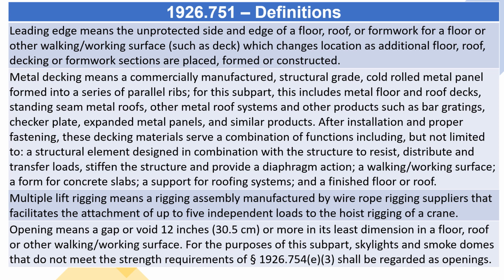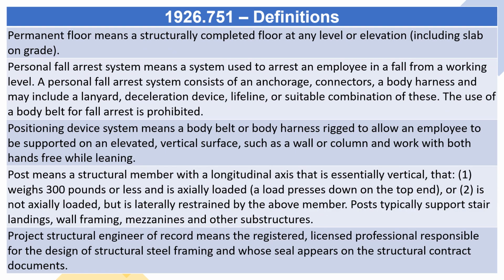For the purposes of this subpart, skylights and smoke domes that do not meet the strength requirements of Section 1926.754(e)(3) shall be regarded as openings. Permanent floor means a structurally completed floor at any level or elevation, including slab on grade. Personal fall arrest system means a system used to arrest an employee in a fall from a working level.